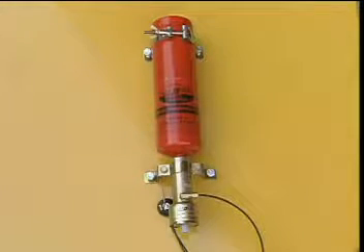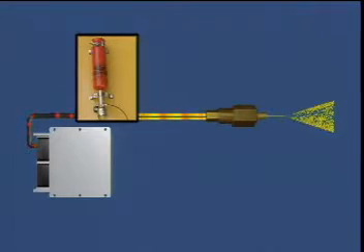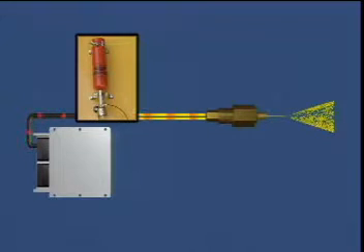Two types of ether injection systems are typically used. The measured shot system cycles ether injection on and off, each cycle lasting a calibrated period of time. This provides a measured shot of ether each time the sequence is completed. The constant on system provides a constant supply of ether, controlled through an orifice.